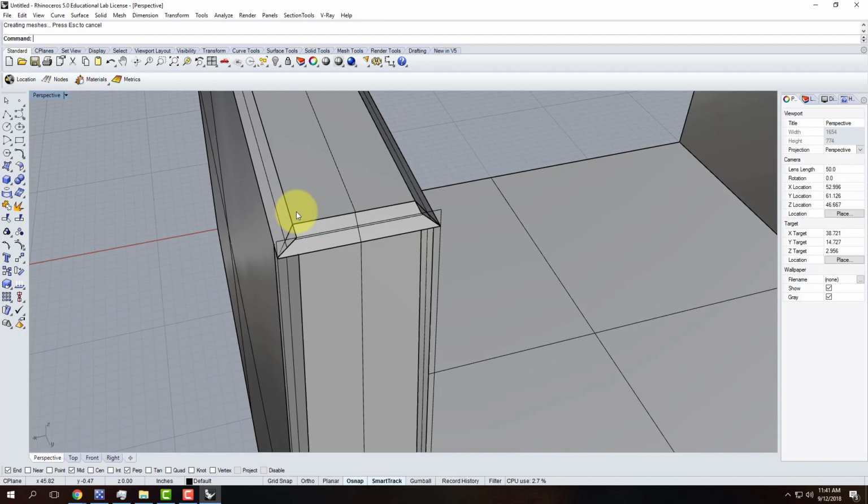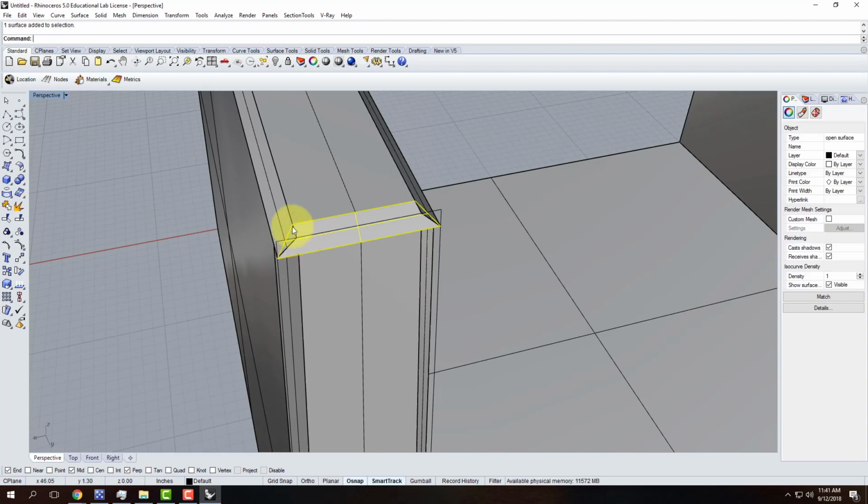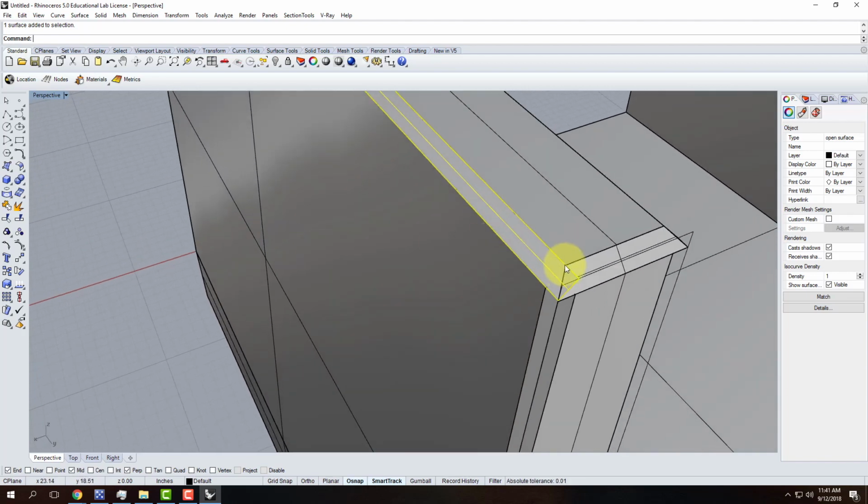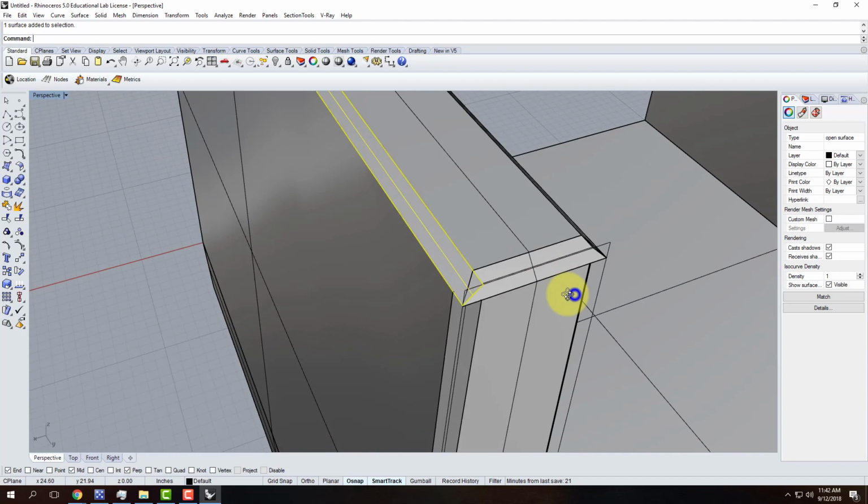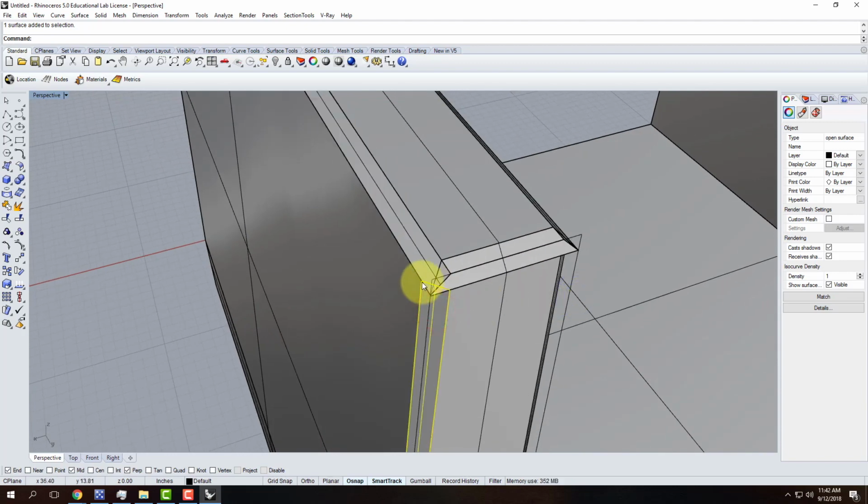I got a bunch of intersecting surfaces, and part of the purpose of today is you're going to have to learn how to manipulate and work within Rhino to see what's happening in 3 dimensions. In this case, I have a surface that's kind of a trapezoid shape here, where this is extending out straight. I have another surface that's straight, extending out straight. It's not angled. And I have this surface coming up here that actually ends pretty much where it's supposed to end. So what I need to do is figure out where this exists in the middle such that I can trim off those extra pieces.